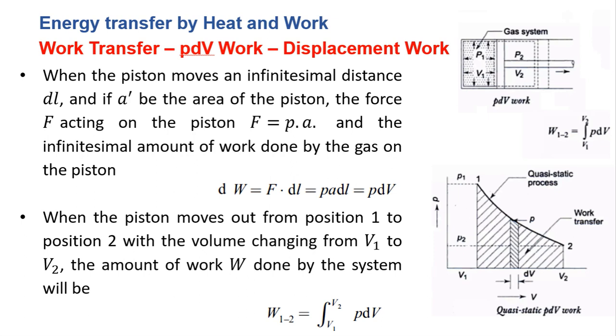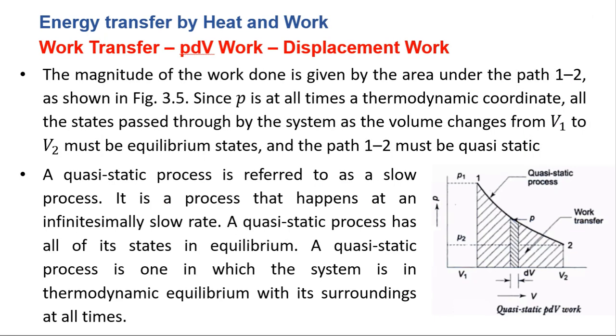Similarly, when the piston moves out from position 1 to 2, the volume changes from V1 to V2, and the amount of work done can be represented as W1-2 equal to the integral from V1 to V2 of P dV.